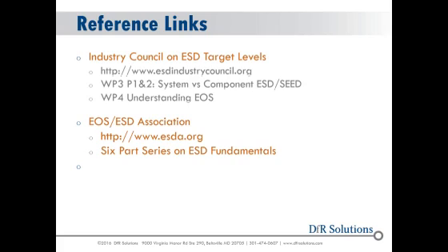pulses, or certainly a cable discharge event, where you can actually get triboelectric charging within the differential pairs in the cable if it's loose, just by wiggling it. And some of those cables you can generate several hundred volts on the pins, and then when you plug that in, it's a direct discharge of that large capacitance in the cable into the device, and that can cause EOS as well.